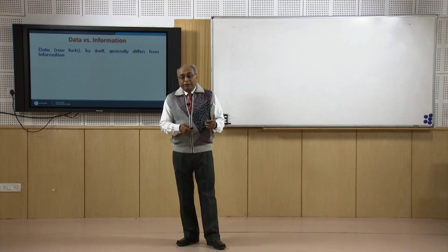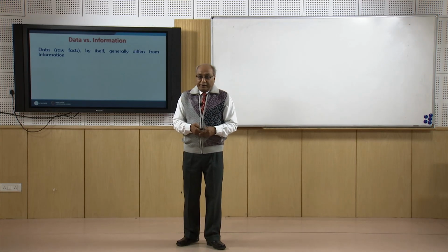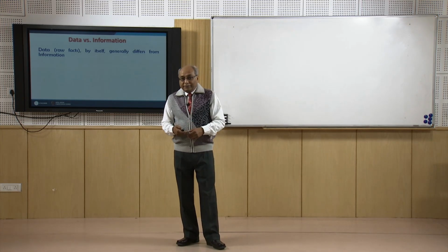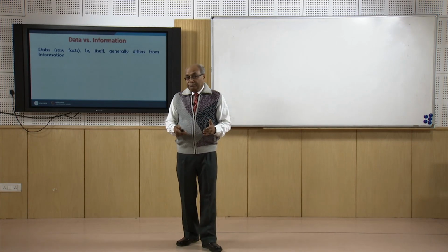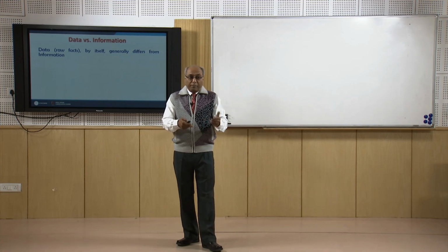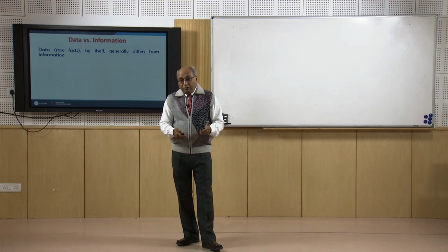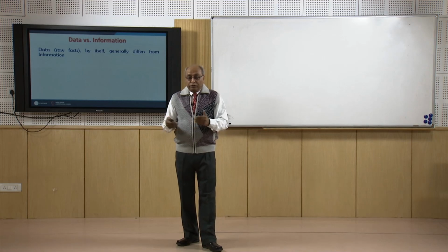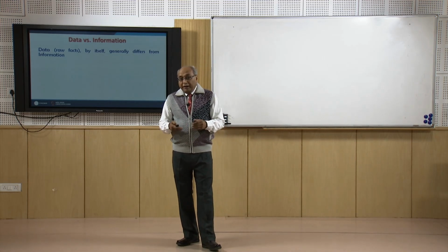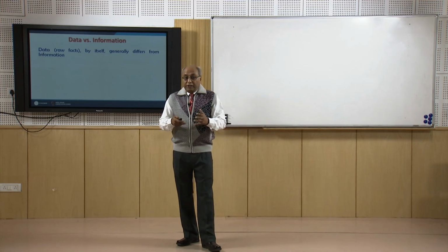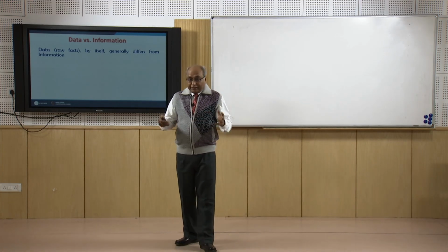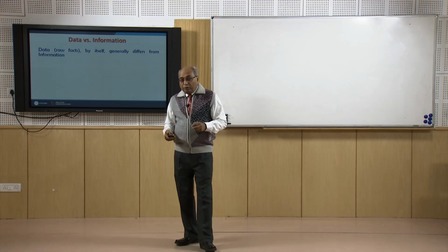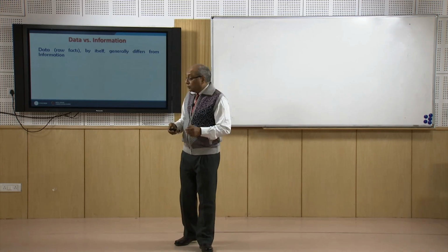Suppose somebody has gone in the field and collected water sample data. Now if he has collected 30 samples from different areas, then I want to see the distribution. So I will try to plot the map on a GIS platform in the form of a map using geographic coordinates, and this will start giving me the clustering information and other things, whether the data has been collected uniformly or collected from only a small area and so on and so forth.